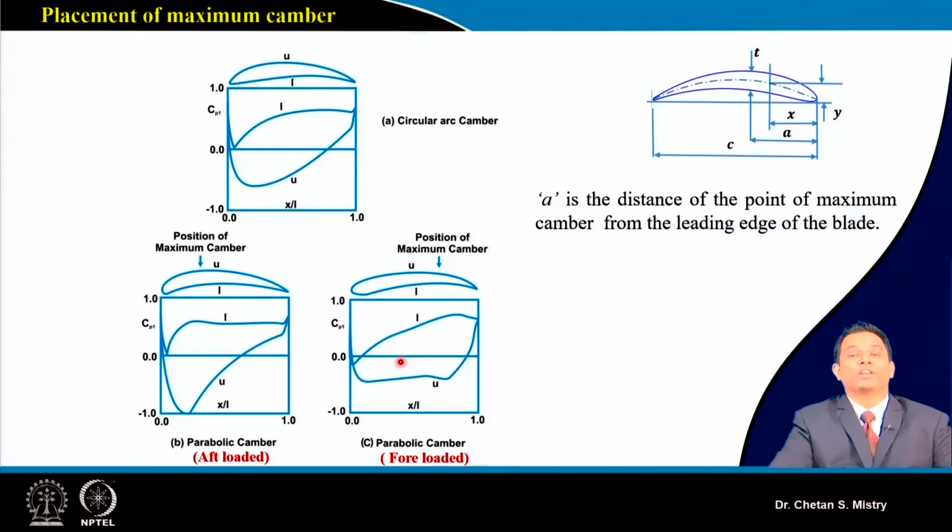Using a numerical tool, they take this available CP distribution and then, based on that, develop a new kind of aerofoil. That is called inverse design. It is also a hot topic for research. People have been working on that topic for a long time, and now we are having again and again the addition of new blade aerofoils.